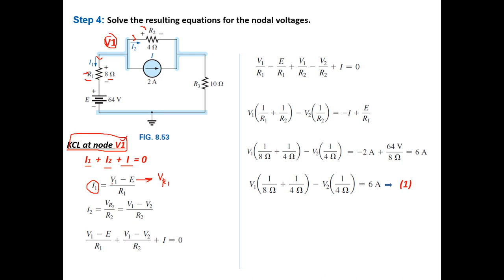So it's the potential difference between the highest point, because we already said that when I'm working with a node, I will consider its nodal voltage as the highest point. So the potential difference between the highest point minus what? The lower point, which is E. So from here to here. So this is the voltage drop across resistor number 1 over its resistance, which is R1. Done.